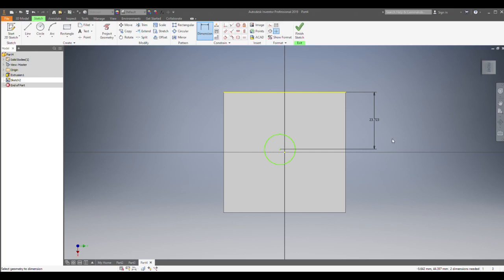So all I did there was click 3 times. I'm going to make this half of my object, so I'm going to make it 25. Because the object is 50 wide, and I want to lock it in place left to right now. So same again, clicking here and clicking the centre, moving it up 25.